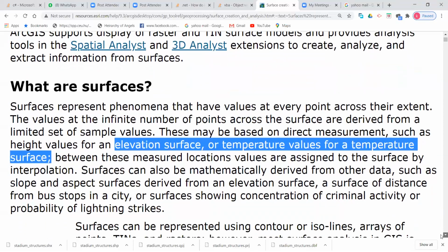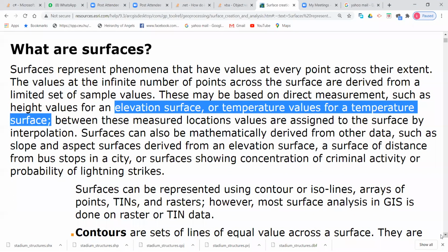Now, another way to extend and to create more values between the sample values is to use what we call interpolation. I believe you all have heard that word before. In other words, you are trying to find the unknown value between two known values. Are you okay? So that is what happens with surveyors going to pick spot heights and then architects asking for those spot heights and trying to interpret what they are, and say, okay, it means we are sloping this way, and so I need to have my building on the other side of it.